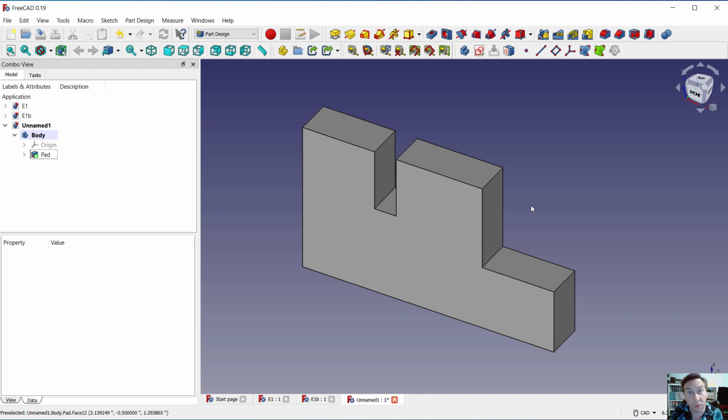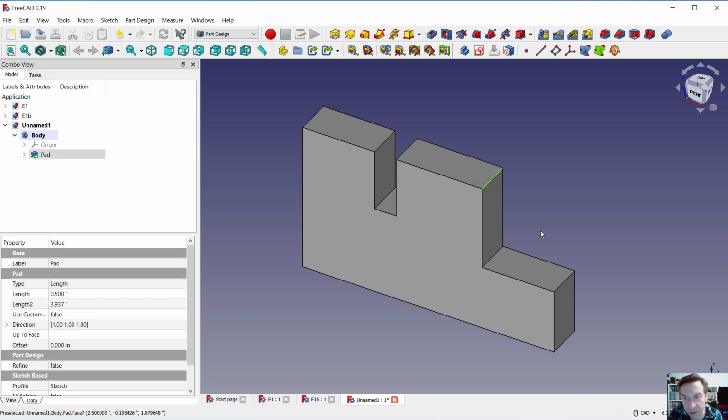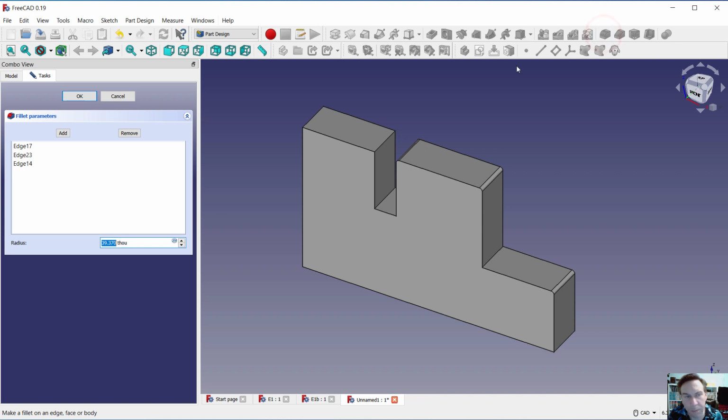Now, what I would recommend, if those of you who are just hobbyists, do whatever you want, but I would tinker with some of these settings. Remember, like, pre-select, like if you want to put fillets in, hold control and pre-select any areas. Like you can select, I can't get that little one in there very well, but let's go to fillet, and then again 1 inch.